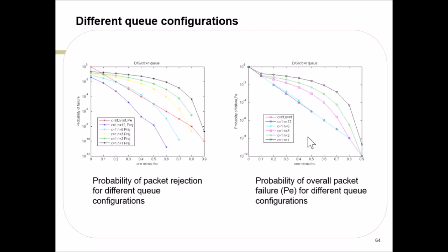So when you read a bit, you can do a hard decision that's either 1 or 0. But now we are assigning a probability whether that bit is 1 or 0 using some soft information. In the floating point simulation, that's effectively an infinite number, a single or double floating point. But when we do fixed point, it's usually 5 bits or 6 bits. That number is what we get from the detector branch metric.